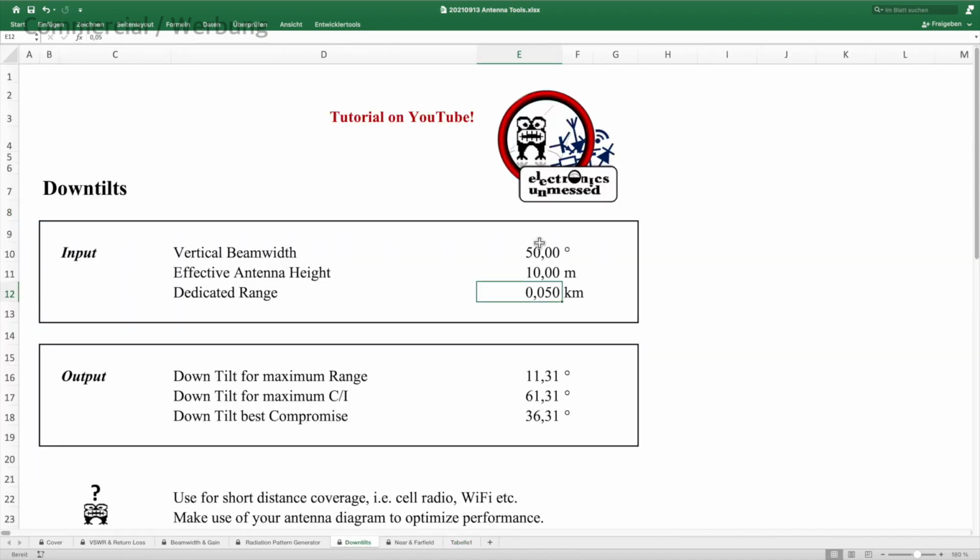In many cases there is room for improving your radio coverage by tilting your directional antenna. Let's say you want to cover the area next to your house with Wi-Fi. You got a directional antenna with 35 degrees vertical beam width for your router. You mounted the antenna to the building at about 5 meters height. Your desired range shall be 50 meters from the house maximum.